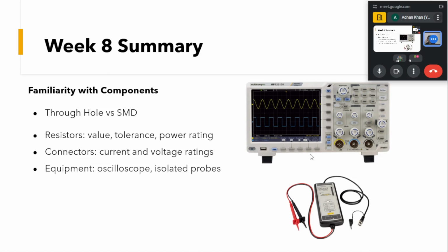But one thing to keep in mind is that usually the probes of all these channels of this oscilloscope are connected to the common ground. That means the grounds of all these channels are the same.